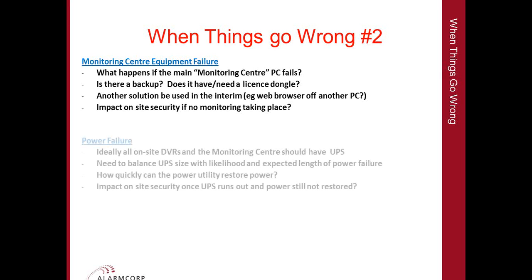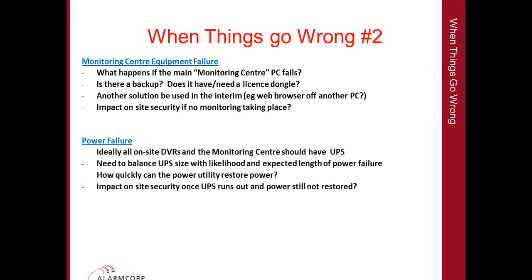Power failure. Ideally, we want all DVRs on site and the monitoring center on a UPS. Now, we need to balance the UPS size, and hence cost, with the likelihood and expected length of power failure. How quickly can the power utility restore power? And in the case of a remote site, this may take some time.